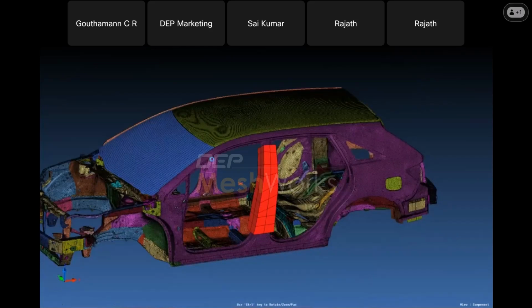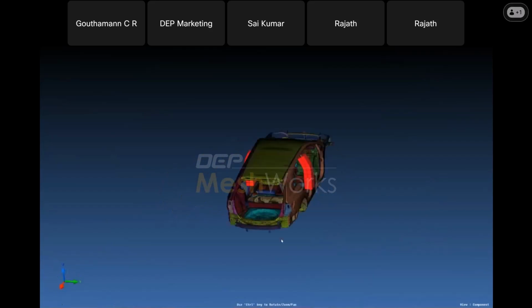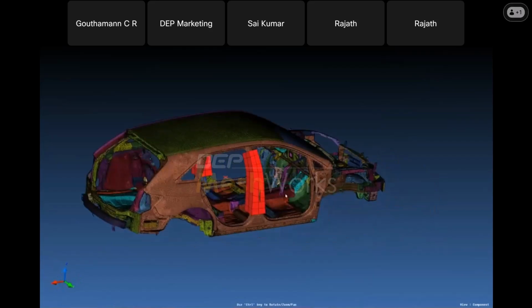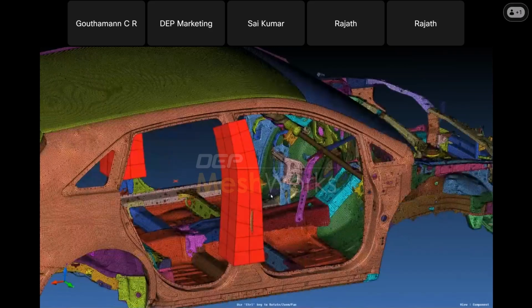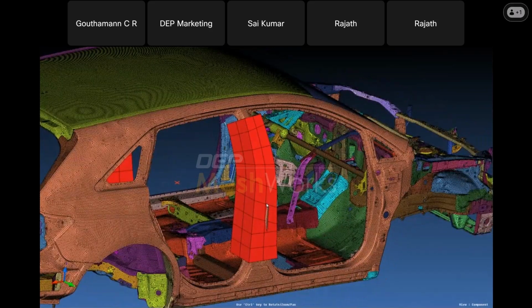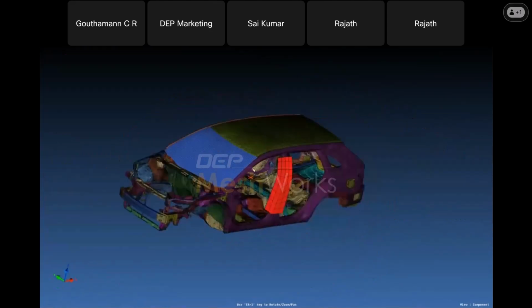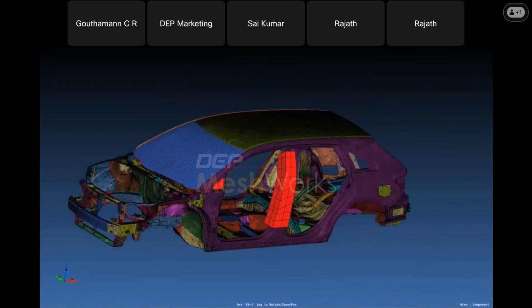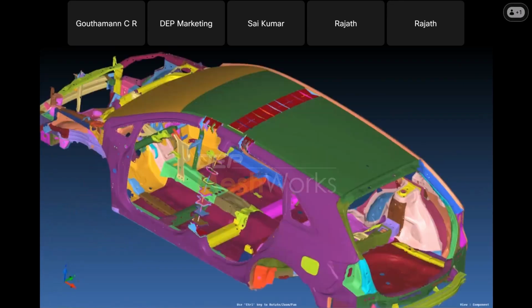It will automatically reflect the block to the other region. And again, we can make sure that the block is covering this region by doing a block adjustment. So the first step is to create these blocks. The next step would be to create the beams.